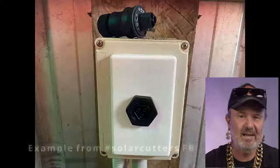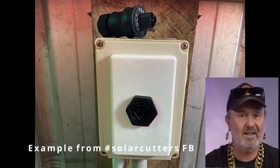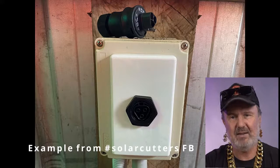It doesn't have pilot pins, but it's got another solution. Many inverters actually have a screened to IP4X AC installation coupler. That means you can plug it in, and it's locking often, which is another bonus, so it can't be accidentally unplugged. The male pins are screened, so there's no live parts that can be touched, and it's regularly used on grid-connected interactive inverters, interacting with the utility grid.